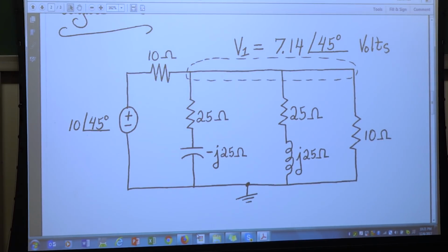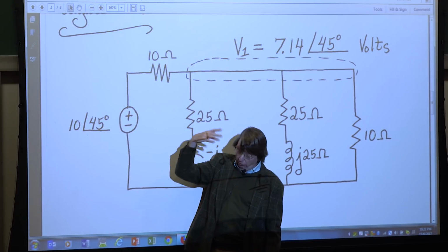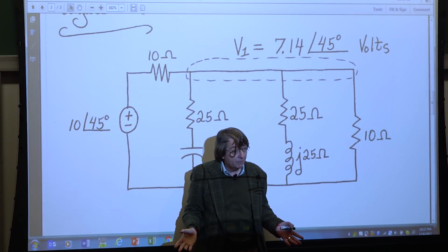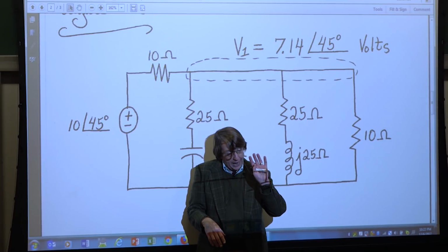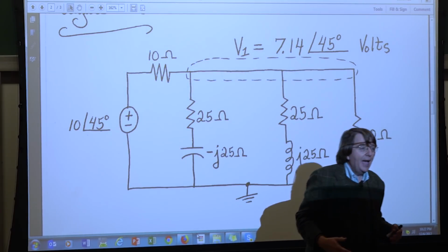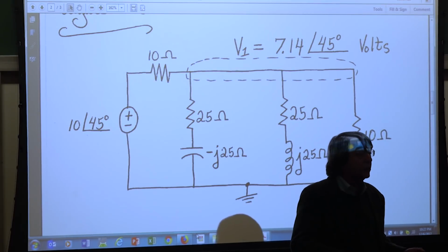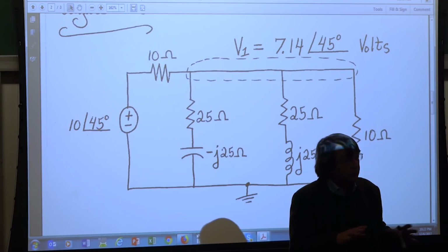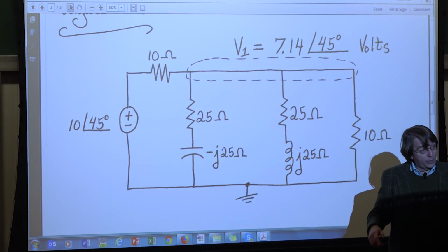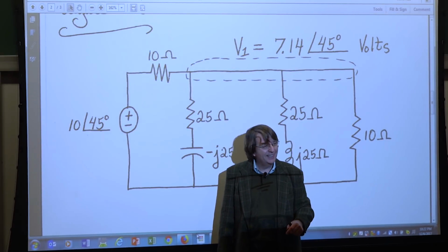Right? Am I getting your contribution? No, I get confused all the time too. Don't worry. So, Sarita, this is a very practical circuit because we can argue, and we're right, that a voltage source has internal resistance. So you often show it as an ideal voltage source with a resistance. Your car battery has internal resistance, and if you don't start your car for a number of months, the battery's dead. You say, well, how did that happen? There was an internal discharge, so we model it as an internal resistor. So this is a very nice and valid model, but could I change it? Absolutely. I could put a capacitor here. Sarita, we're good? Awesome, good.